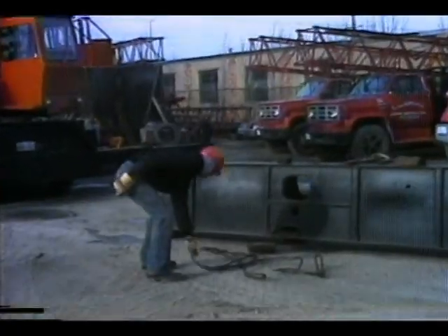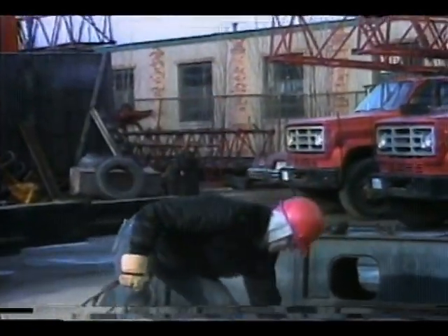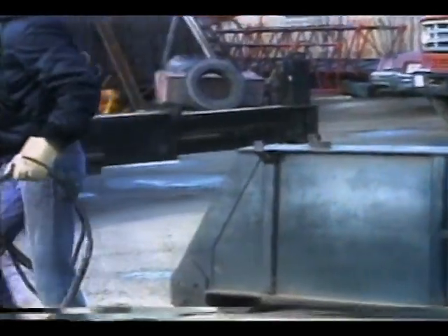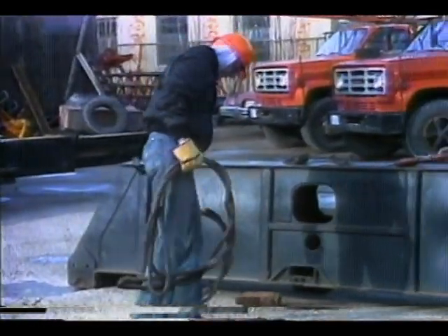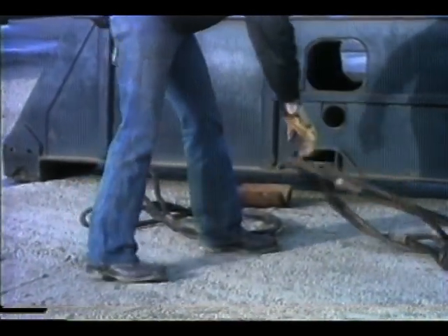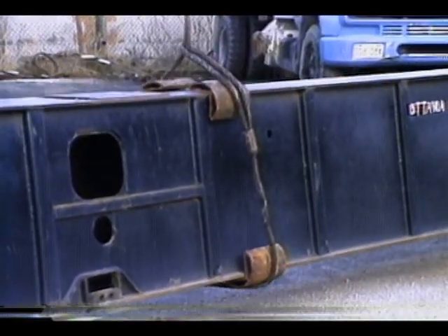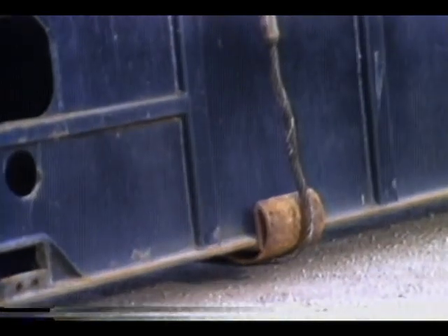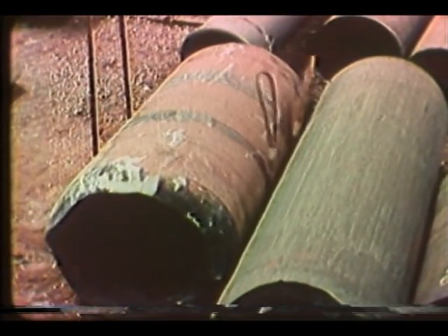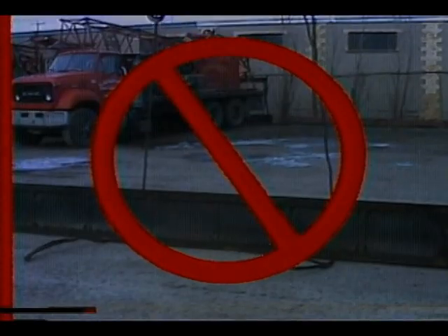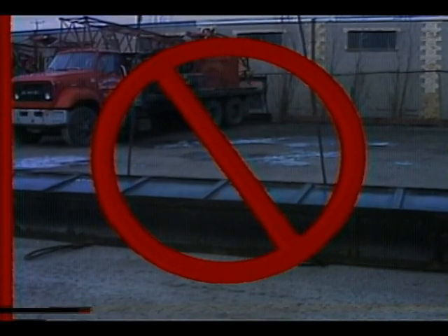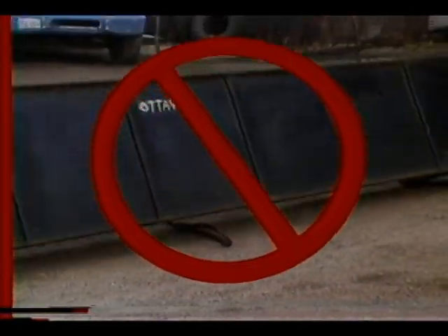Take special precautions and/or use a larger size rope and appropriate hardware whenever the exact load distribution is not known, there is a possibility of shock loading, or there is a hazard to personnel. Use padding or softeners to protect rope from sharp corners or edges. Never drag the rope from under loads or over obstacles. Always use blocking under the load. Avoid dropping the rope from heights. Never roll loads with ropes.